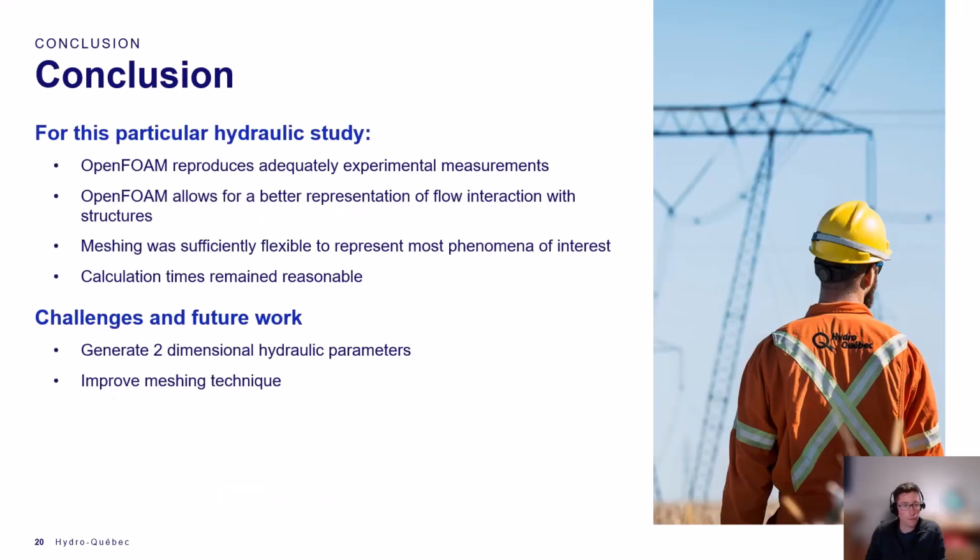In conclusion, for this particular hydraulic study, we found that OpenFOAM reproduced adequately experimental measurements. It also allowed us to better represent some of the flow interaction with structures that we usually don't take into account in our studies. The meshing was sufficiently flexible to represent most phenomena of interest at various scales, and our calculation times remain reasonable.